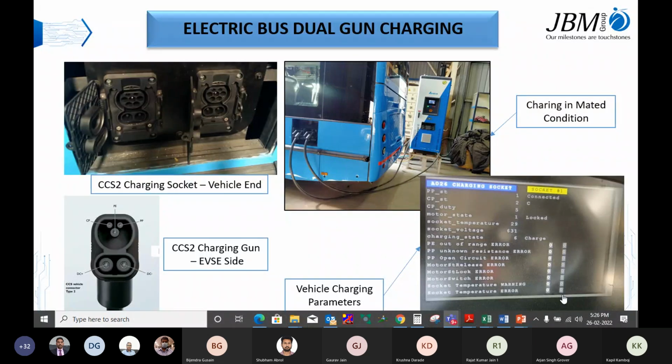If the battery voltage is very low at the start of charging, until we reach the voltage of 700 volt and about 95% SOC, it will go in constant current method. It will increase the voltage on and on, but the current will remain the same, 200 or 400 ampere. After attaining a voltage near the maximum voltage, it will change to the constant voltage method, so that it can send limited but variable current to balance the cell.